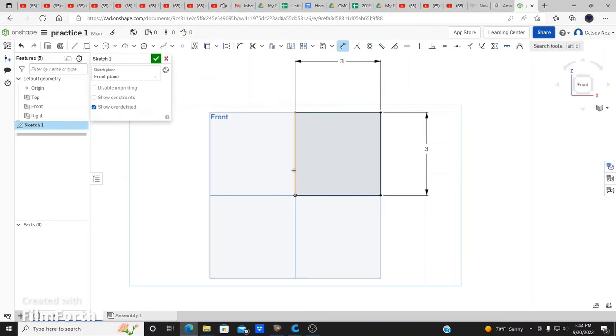If you go to do the remaining dimensions out here, don't do it, because it will overdefine the boundary itself and lock it right away, telling you that you're overdoing it. Why would you want another dimension if you already have one over here? In the future, if you're adding a dimension and there's an error that tells you you're overdoing the commands, it means you did a command before that you did not know about, and you have to find it and get rid of that command to get back to your last dimension and fix it. We'll look at that along the way. We'll have another blueprint. Right now we're just going to do the basics.